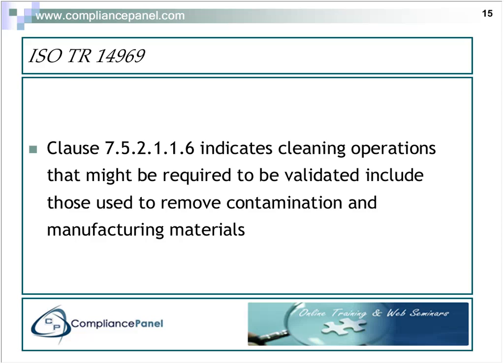Unfortunately, they changed to a fluid which had some results where it remained on the product, got out into use, and in this case, the product was a dialysis filter. It filtered the patient's blood during the dialysis of those patients, and it resulted in the death of 27 patients around the world because this particular cleaning process had not been adequately validated to demonstrate that all of the residue was removed.